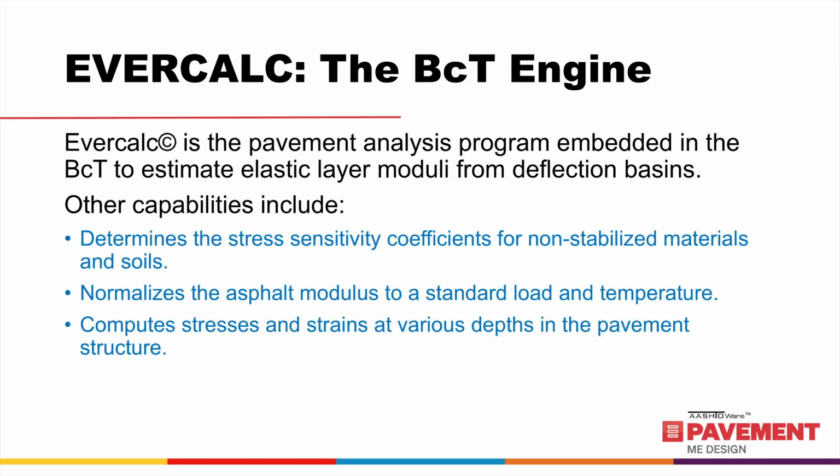Now let's look into EverCalc, the engine of BCT. EverCalc is a mechanistic-based pavement analysis computer program that is embedded inside the BCT to estimate the elastic moduli of pavement layers from deflection basin data. It uses the backcalculation method or approach. The program has been primarily used for the analysis of flexible pavement using FWD deflection measurements, but is applicable to